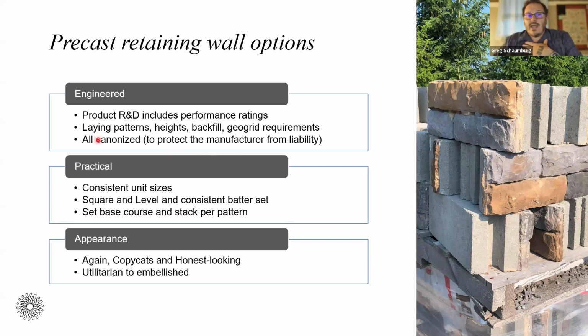But I say all that to say, the performance of a retaining wall is important when it comes to flat work. It's very important when it comes to vertical work. If you've ever seen the memes or the images of retaining walls suddenly giving way and failing, it's not really a joke, but it does illustrate how important it is to make sure you're specifying the right material for the right thing. Good news is every manufacturer will tell you exactly how tall you can build with their wall. And if there's an alternate and the exact construction details, it's all within their literature, either on their website or on the handy brochure that you can get at any of the building supply centers.